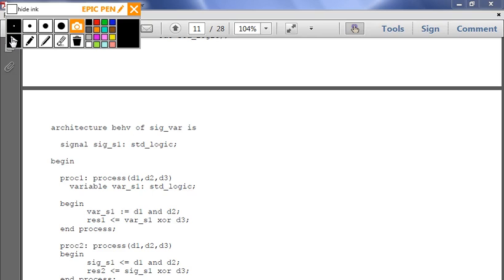It's actually causing the signal to slow down so that at the output, it occurs at the same time. So in your final design project, you can show that you're using K-maps to reduce the race condition. You're getting a little more area, but the result is that the timing comes out correctly. That signal from the AND gate reaches the XOR gate before that XOR gate propagates. Bingo. Okay. Exactly right.